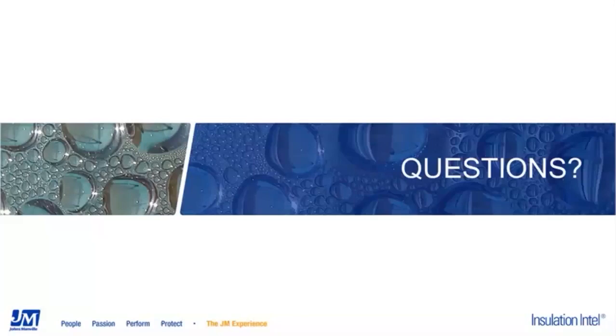The most important thing to note is that insulation does not stop the flow of heat. It only slows the flow of heat. What that means from a freeze protection point of view is that no matter how much insulation you put on a pipe, it cannot prevent freezing forever. It can only prevent freezing for some certain amount of time. So the best way to handle this in an extremely cold climate is through proper calculations, if it's a flowing pipe.